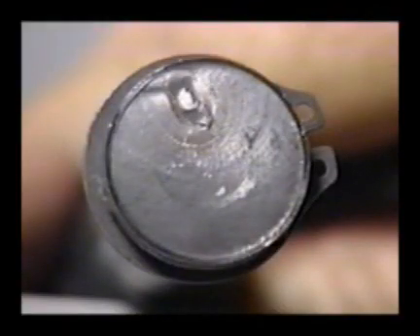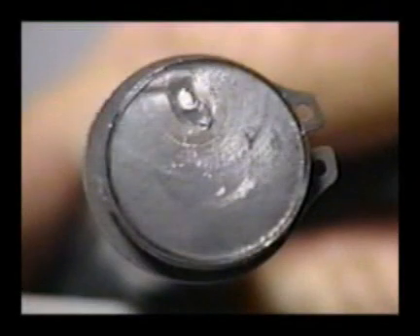Beach mark patterns on rotating bending fatigue fractures can be confusing, since they often surround the final fracture, giving the appearance that it is the initiation site. Notice that the beach marks are more widely spaced and distinct near the final fracture. Careful examination with different lighting angles reveals that the beach marks actually start at the lower left, nearly opposite the final fracture, and that the curve of the beach marks reverses due to the high stress at the part's surface and low stress inside.